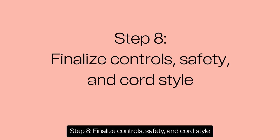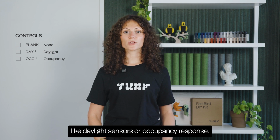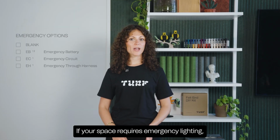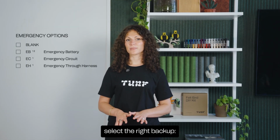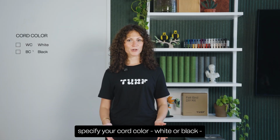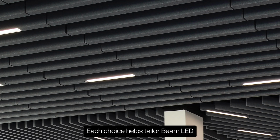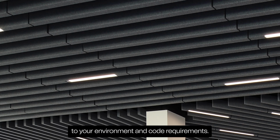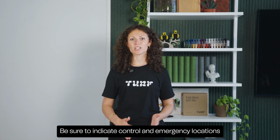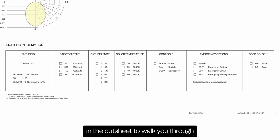Step 8. Finalize controls, safety, and cord style. Now, choose any optional lighting controls you need, like daylight sensors or occupancy response. If your space requires emergency lighting, select the right backup: emergency battery, emergency circuit, or through harness. Finally, specify your cord color, white or black, to coordinate with your ceiling aesthetic. Each choice helps tailor Beam LED to your environment and code requirements. Be sure to indicate control and emergency locations in your product layout. There's also a handy checklist in the cut sheet to walk you through every lighting spec decision with confidence and accuracy.